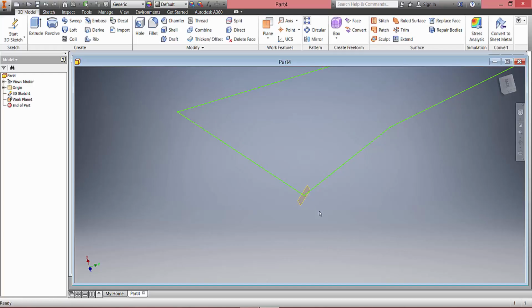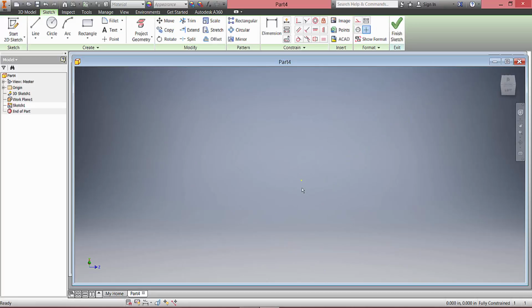2. It'll create a plane over there, and then I'd like you to start a 2D sketch on that plane. Might have to zoom in a little. Sorry for that. Zoom in over there, and I'm going to draw something like, let's say, a circle. I'm going to draw it just like we would a normal sweep.